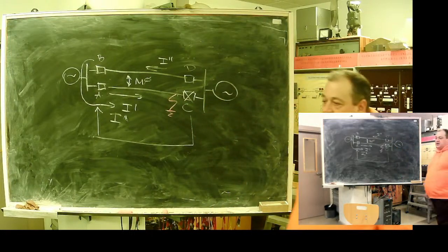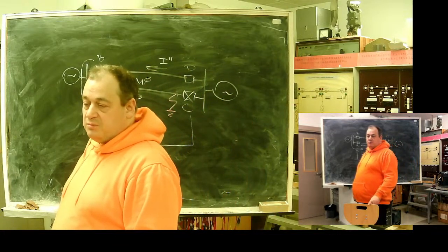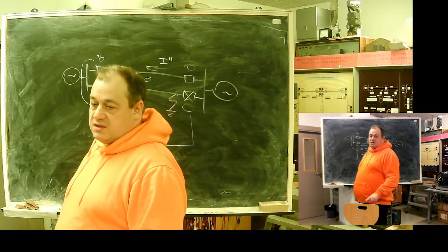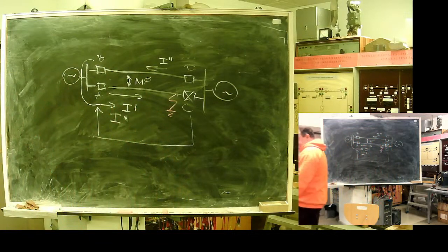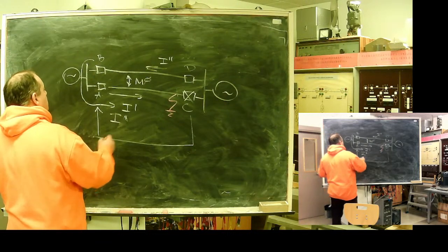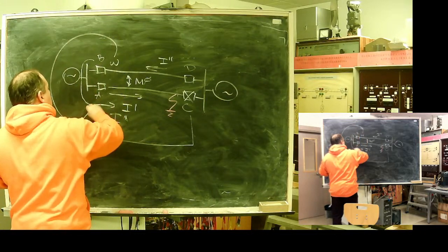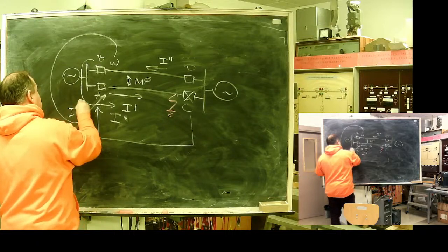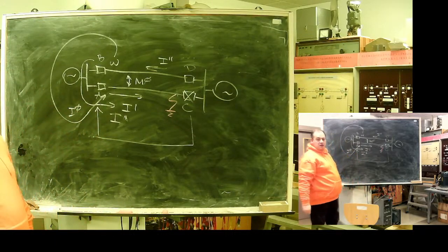Modern relays have one measure to fight this problem of zone movement due to mutual inductance. Modern relays have ability to take zero current of parallel line.